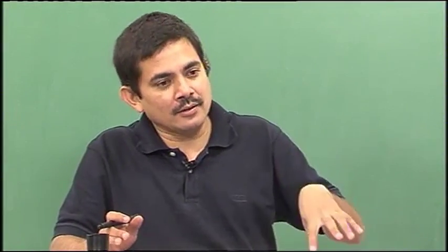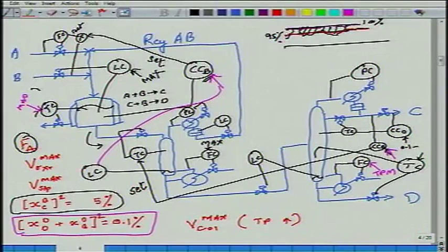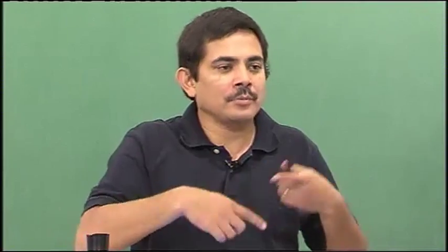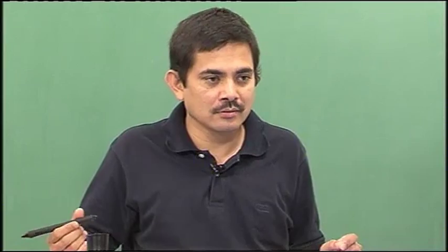Okay. But the point is, conceptually, this is how I would rather do it. If it turns out that the level controller is fragile, I will have to give up on tight control of either boil up on the stripper or boil up on the second column. Something will have to be given up, because it is turning out that my level control is fragile. Does this make sense or no? Okay. We will take care of that maybe next time. If the reactor is not a CSTR, it is a plug flow reactor, well, there is no residence time, this will work, guaranteed it will work, no problem.